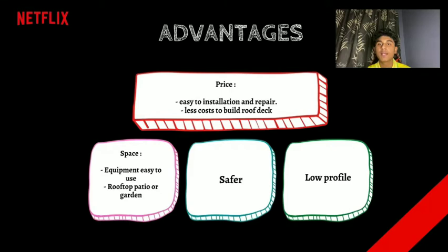The same applies to repairing a flat roof system. Patches are available for the various flat roof systems, so it takes less time to repair. If an asphalt shingle needs to be repaired, for example, if a tree branch punctured it, often the surrounding shingles need to be repaired as well.